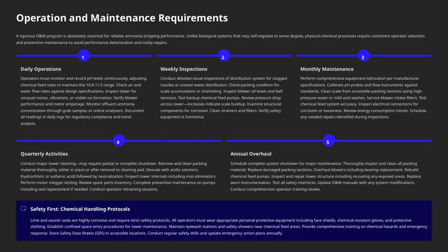They typically involve a major cleaning of the tower, which might require shutting down the system partially or completely. Remove and thoroughly clean the packing material, either in place or after removal to a cleaning pad. Descale with appropriate acidic solutions, like hydrochloric or sulfamic acid, followed by neutralization.